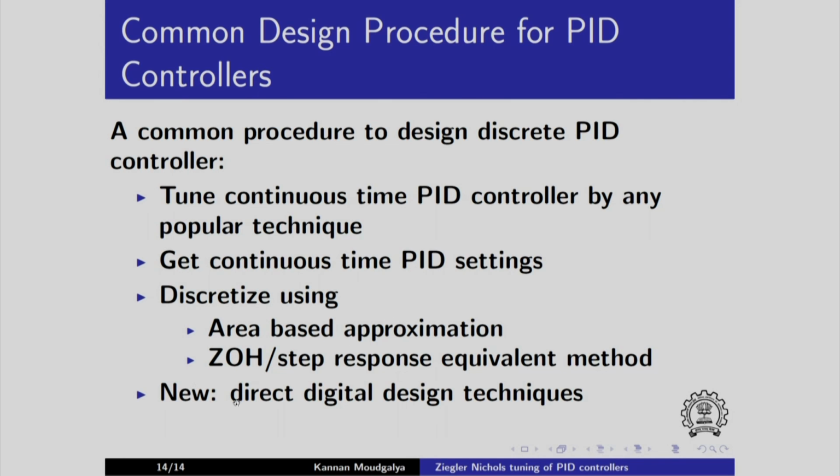There are also new methods. Directly design the PID control law in discrete time domain and then map them into PID controllers. The method of discretization that we will discuss in this lecture will be important. There are many plants that already have continuous time PID control settings, but they have difficulty in discretizing. With a good theory, discretization becomes straightforward.